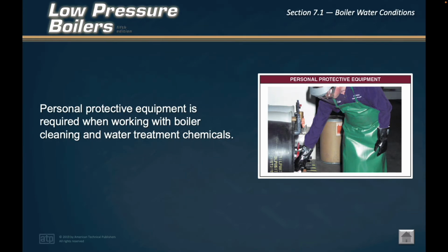A boil out is a process of boiling a solution of water and cleaning chemicals in a newly installed or repaired boiler. The cleaning chemicals are replaced with fresh water after the boil out procedure is completed. After initial startup and boil out procedure, a water treatment program to be followed during normal operation is established. Whenever working with boiler cleaning and water treatment chemicals, proper PPE must be worn, including eye and face protection, gloves, and other required protective clothing.